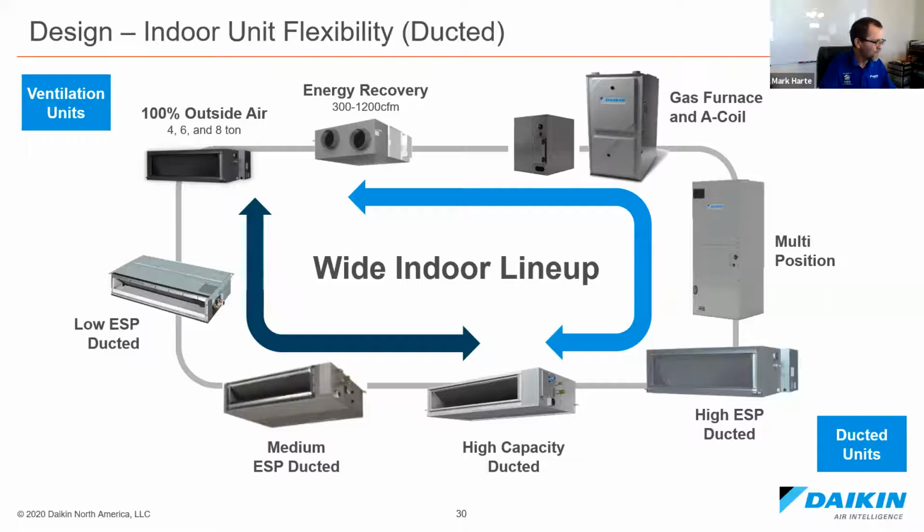Now our ducted fan coils, these are all ducted. This is low static. You're not going to get more than, I think, 0.16 static off of this when you change it up to the higher static. Now the FXS, the medium static ones, we can do an auto static setting, and I'll talk about that in a little bit. So this will be the SQ and the MQ. These two are almost the same style, but you get more static out of them.